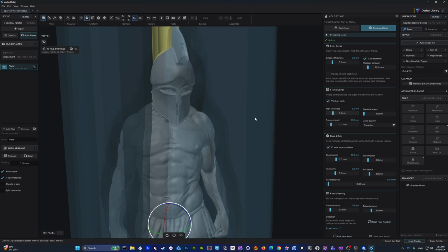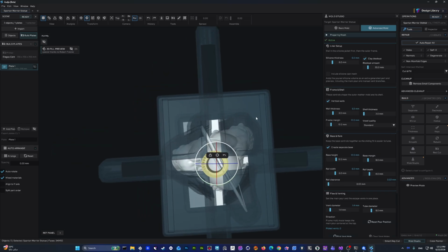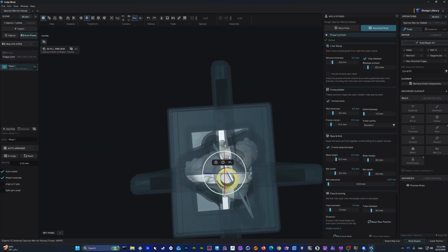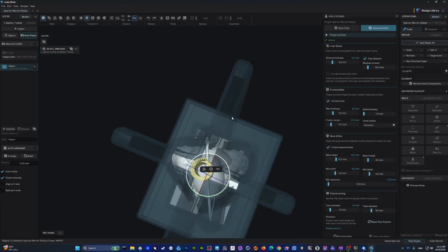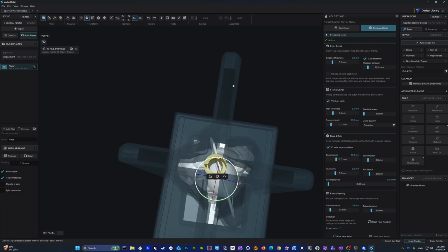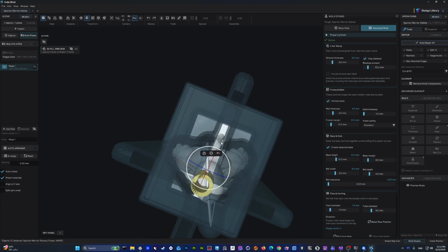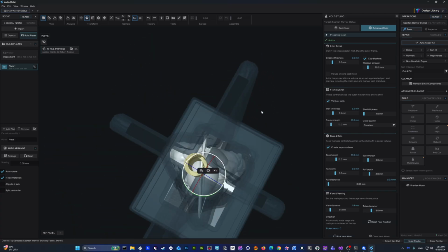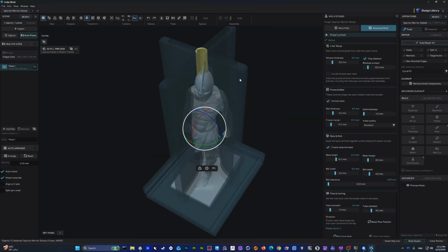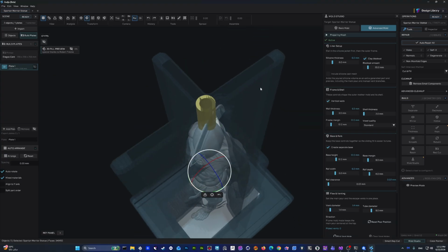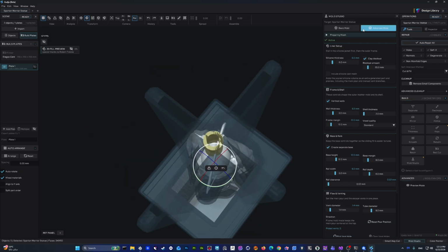As you can see, these walls, let me show from up. Why are we making these walls? Because after we generate the mold, this part will be filled with the silicone, so you will need to cut without touching inside the mesh or the original model. So while we are printing in real life, you're actually printing the actual 3D model, and you are also printing this mold we are gonna make. So that's the difference between basic and advanced mold.